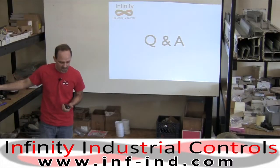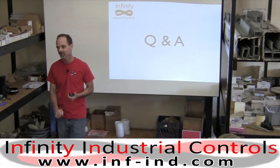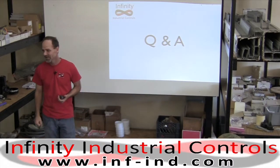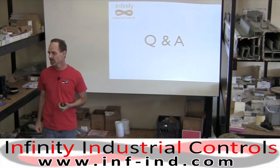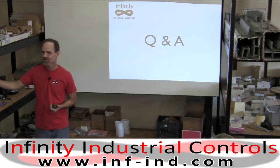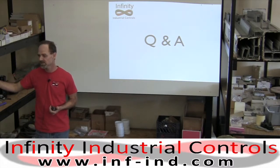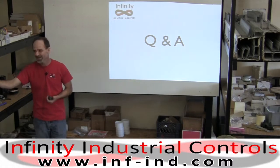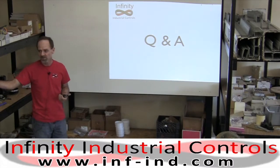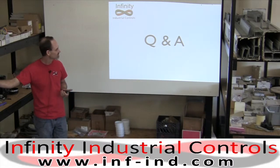The thing about DC is when you first start up a DC motor, it'll deliver you full torque right now. AC motors don't do that. The AC motor gives most torque when it's at its designed speed. So some applications need full torque at very low speed, and that's where you'd want to use a DC motor. They're getting better with the AC though, and they are able to generate a lot of torque at slow speed now, because of the technology of the variable frequency drives.